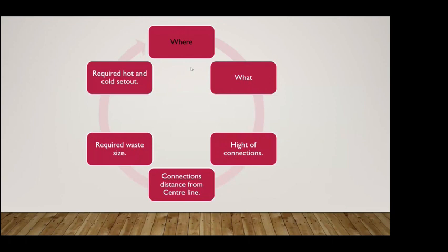Sometimes you can do that, like with a toilet. You can get a specification from the manufacturer. Like Caroma have got an app. They used to have a little booklet, probably still do, a brochure, and that'll tell you, okay, this one's back entry, it's to the right hand side, it's 150 off center. You can do it as a P or an S trap, but if it's an S, it's got to be within 100 to 200 from the wall. So there are all these different things that vary all the time because there are so many different options out there that you've got to consider.